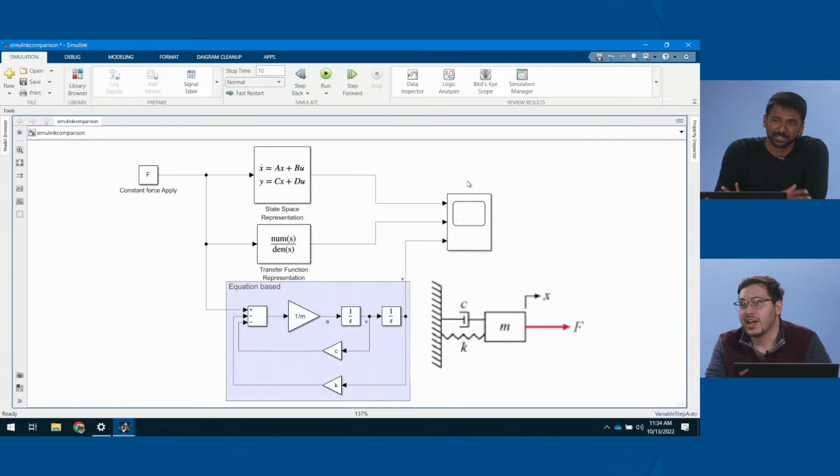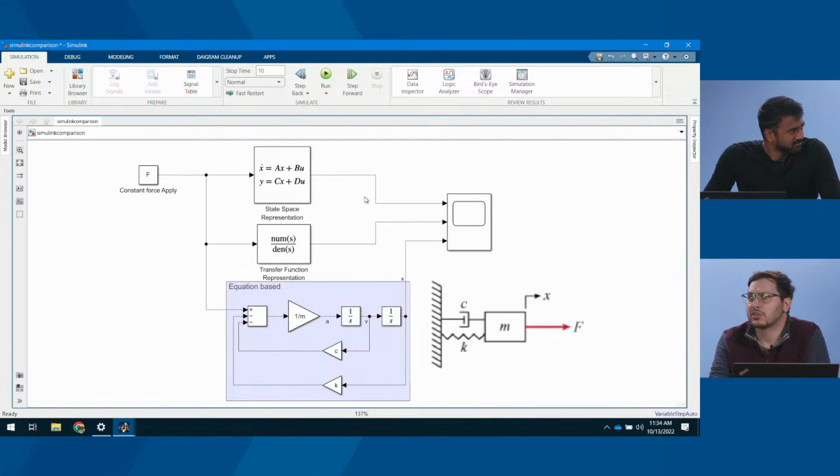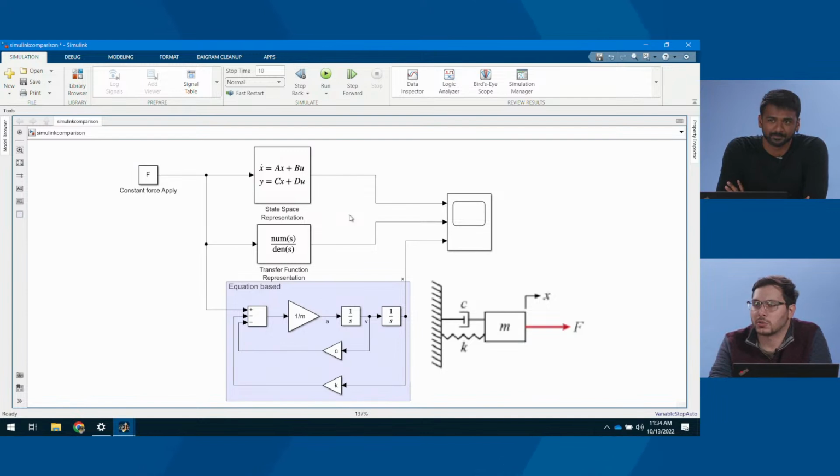So walk me through what you're doing here, Sam. All right. We have a mass spring damper. We got a mass spring damper. Okay. What I wanted to show basically is that back when I took system dynamics, the way that it'll probably be taught if you're taking a system dynamics class, there's really 2 ways that you're probably going to model this, right? And those are either going to be a state space representation or a transfer function. There's different schools of thought of which one to use when, and I'm not trying to start an academic debate about that. But this system can be represented as both.